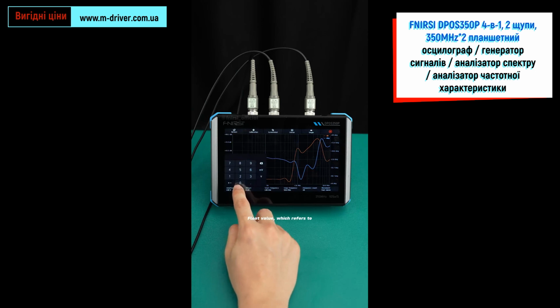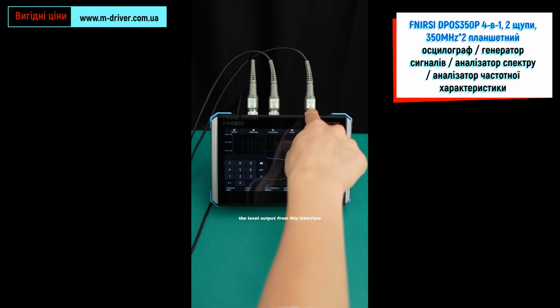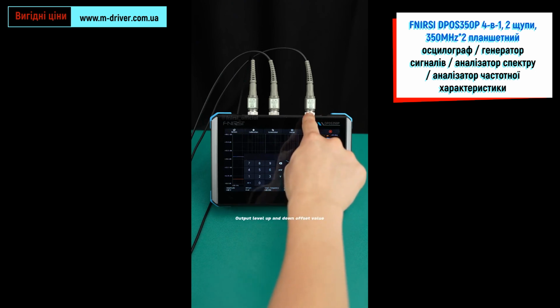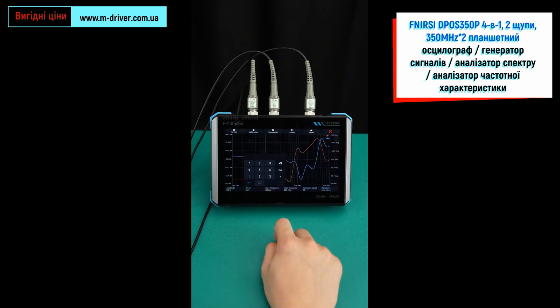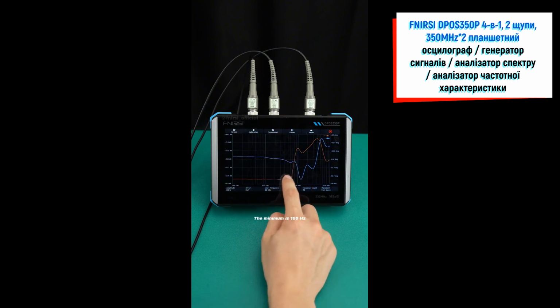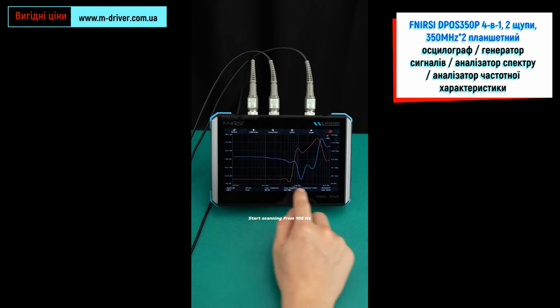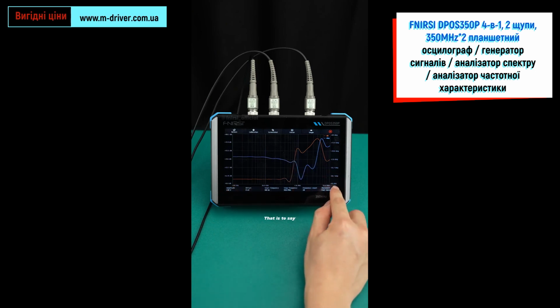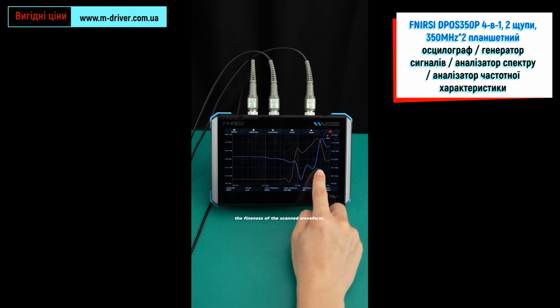Amplitude value refers to the level output from this interface. Offset refers to the up and down offset value of the output level at the output interface. Here is the starting scan frequency. The minimum is 100 Hz, so scanning starts from 100 Hz. The maximum cutoff frequency here is 50 MHz, that is to say, the scan reaches the 50 MHz position. The frequency base determines the fineness of the scanned waveform.